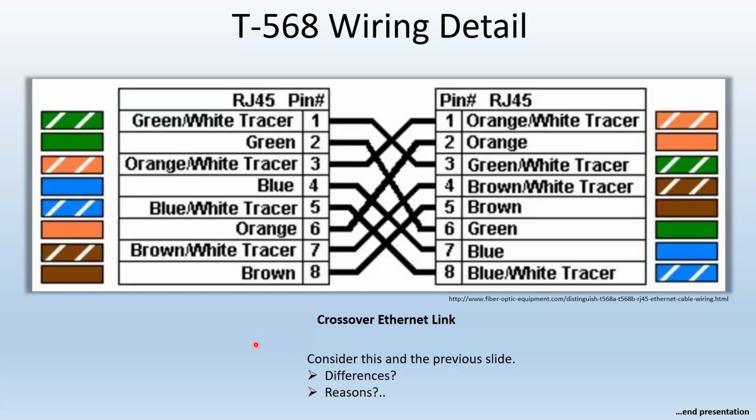Once I had a situation where the instruction was to install the cameras: remove all the old security cameras, install new security cameras, use the existing Cat5e wiring, and replace the wiring only if you have to. So I had to do the testing first with the tester to see if the cable passes or fails, lengthwise, wire mapping, and frequency response. And one cable gave me grief. It came up as a failure, one broken wire.